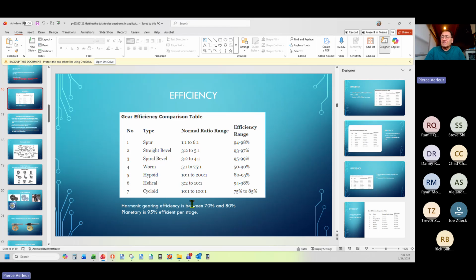Planetary gearing gets expensive. So if you're doing a 100-1 application, you're either on 2 10-1 reduction ratios, so a 2-stage box, plus a lot of derating for the small planet gears in those 2 10-1 stages, or you're in a 3-stage box. Now planetary doesn't look that good when you can do a single stage with another type of gearing.